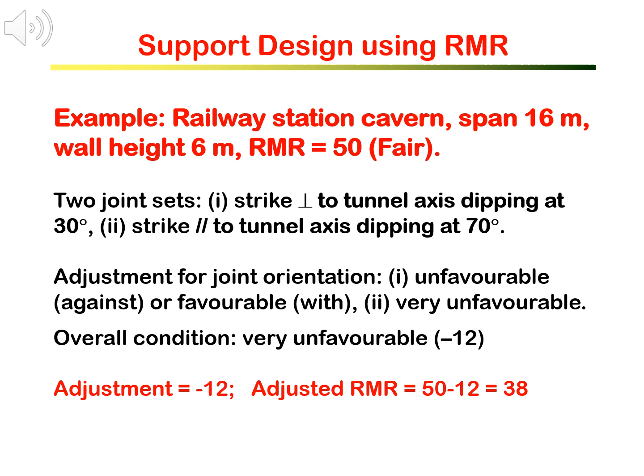First, you need to work on adjustment for joint orientations. By checking each joint set, for joint set 1, if the excavation direction is against the joint set 1, the condition is unfavorable. If the excavation direction is with joint set 1, the condition is favorable.